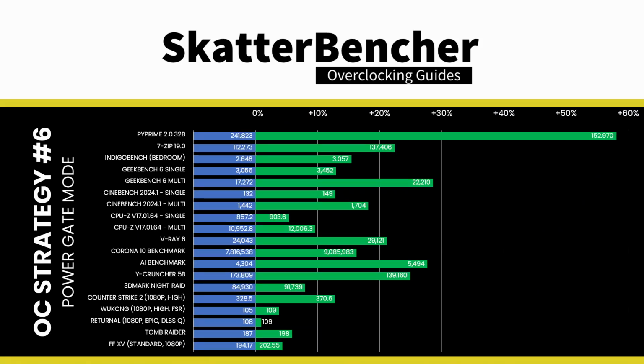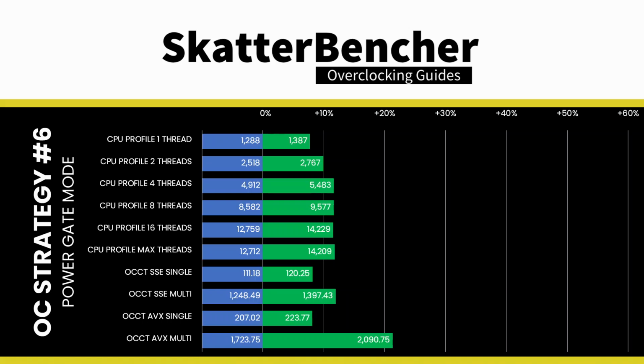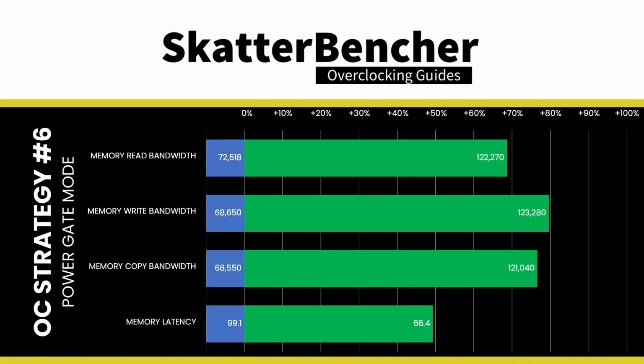We reran the benchmarks and checked the performance increase compared to the default operation. While Power Gate mode isn't officially supported anymore, my experience proves it has a place in Intel's overclocking toolkit for regular overclockers. For some reason, PG mode suddenly enabled the overclocking headroom for P-cores 4 and 5, which added extra multi-thread performance. The performance difference with DLVR mode isn't huge, but it's a lot less effort to get to the same results.